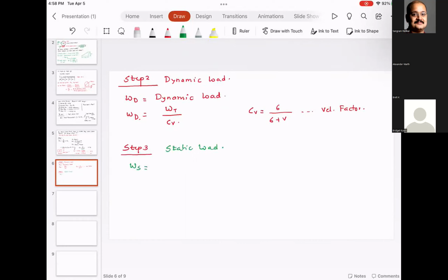The difference here is you are going to have sigma E times B times pi times M times Y. Now sigma E is the endurance strength. And please note, this is not the surface endurance strength, but this is the core endurance strength.